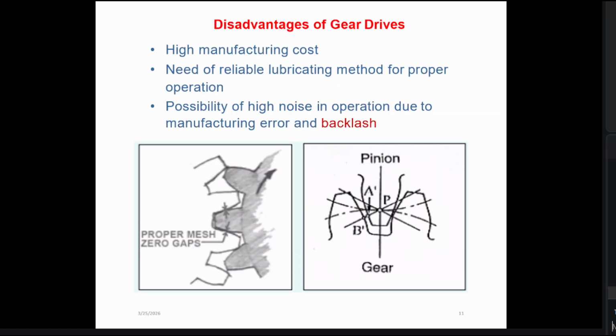Since you are in year two, semester two, you have completed Manufacturing Process One. Yes, CNC, we can use CNC milling or EDM wire cut. Yes, casting, good. Lathe machine. Yes, we can manufacture gears using a lathe machine, but that is not a feasible option, right?